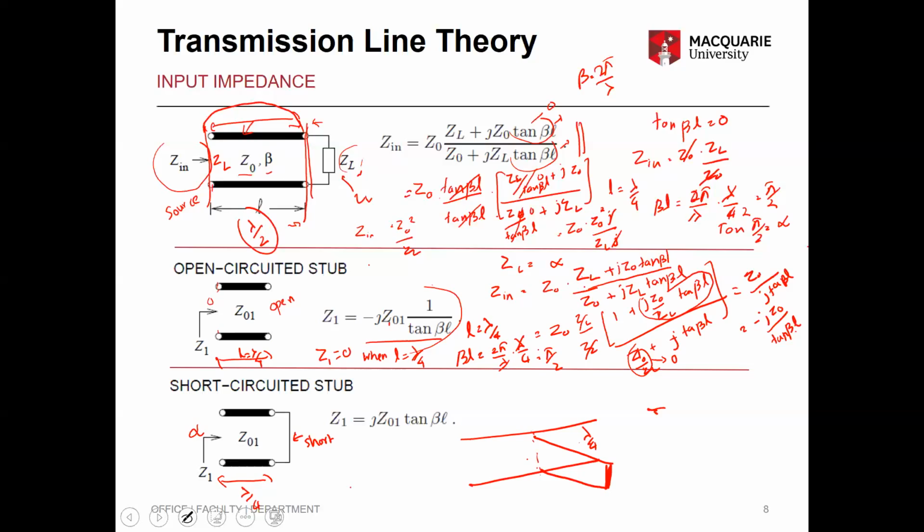So this transmission line has a source and a load, and they don't see this effect. But if you keep this open and it's lambda by 4 at that particular frequency, this becomes short. So the source will not see the load because it's all shorted here. It only sees a line that's shorted at this point. So that's the importance of that. You can short or open certain points. If you pick lambda by 4, you call it a stub.